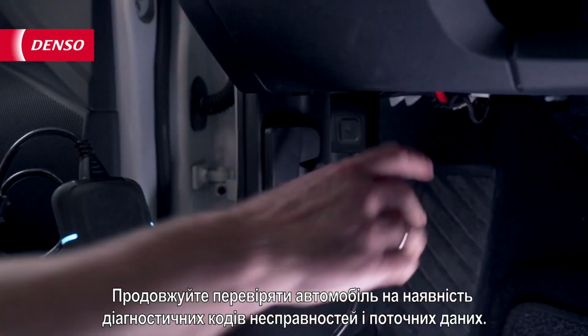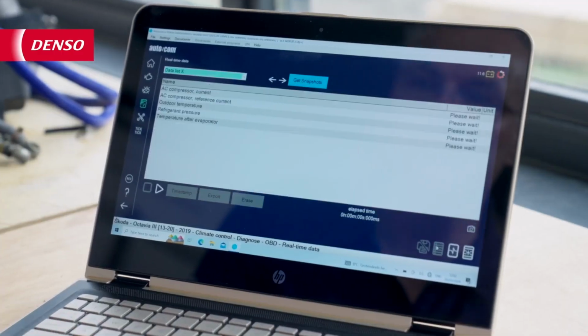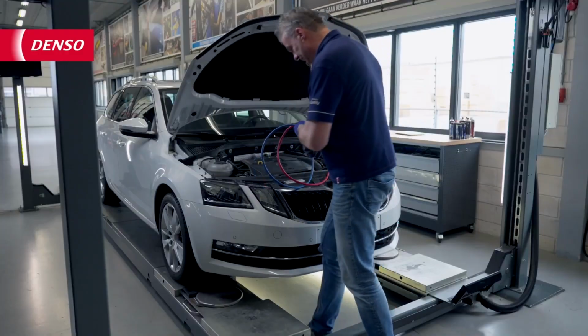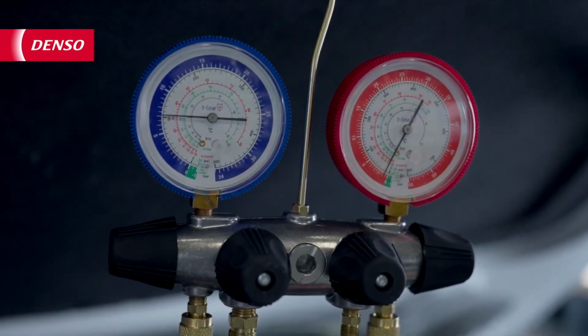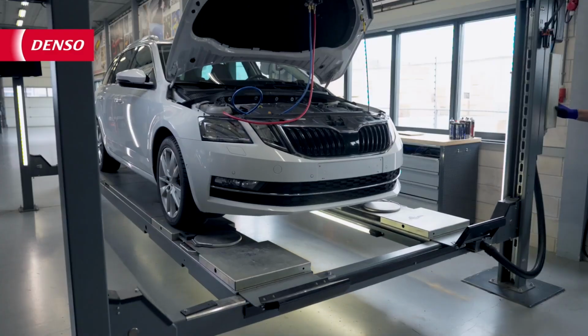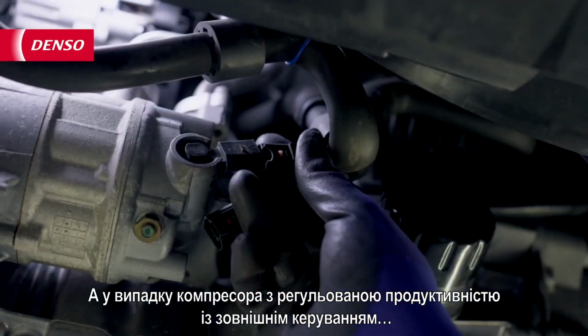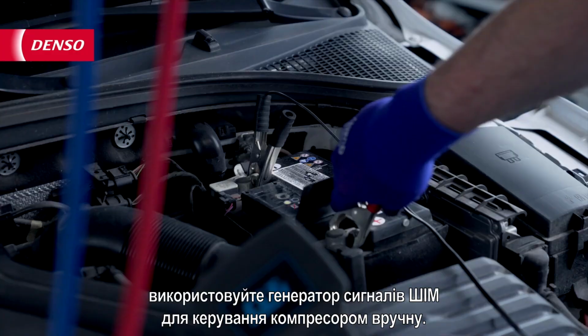Continue on by checking the vehicle for diagnostic trouble codes and live data. Then, check the pressures. And in case of an external controlled variable displacement type compressor, use a PWM signal generator to control the compressor manually.